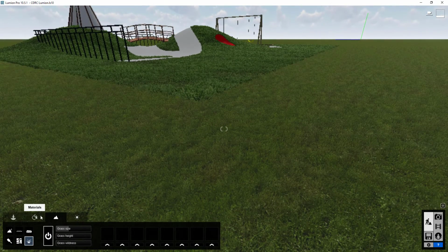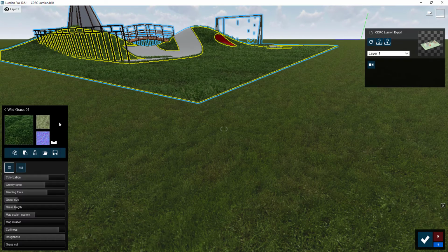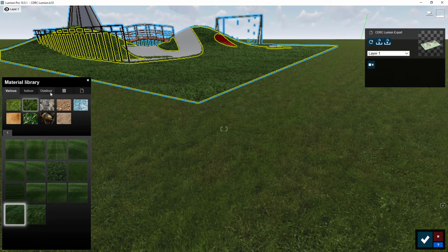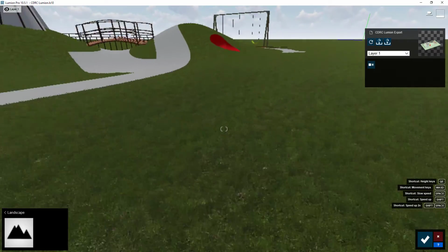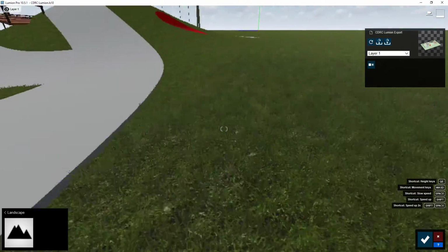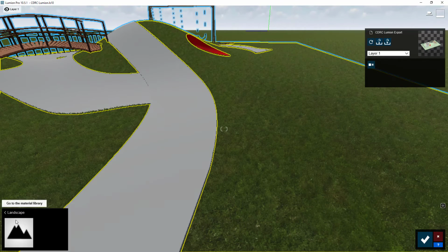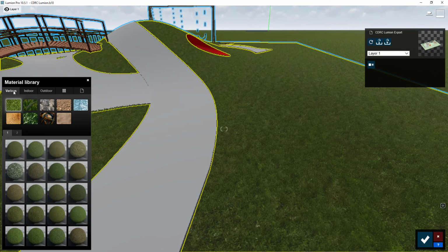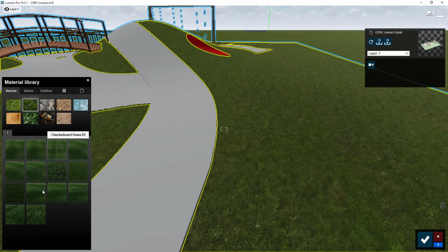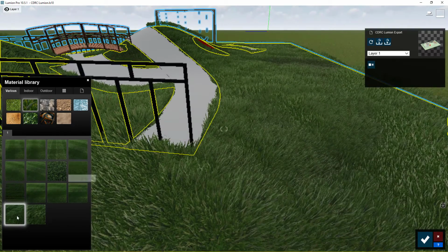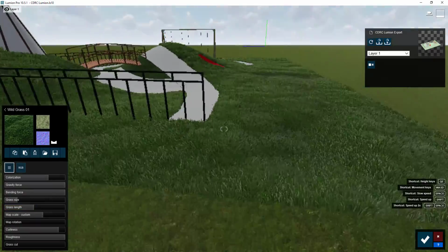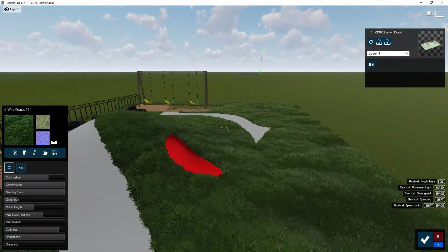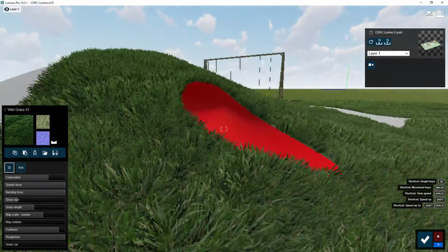But if you want it to match, you could always go inside material, select that material, go back, go to new, and set it as a landscape material. Now they are almost seamless. But for close-up shots, I actually like the other grass, so I will go there and set it up like that. So there you have your 3D grass, which in my opinion looks not so bad.